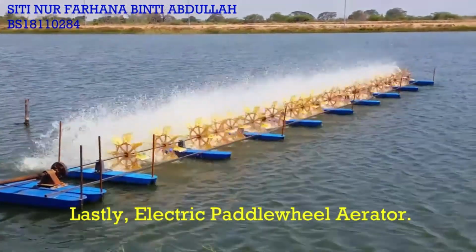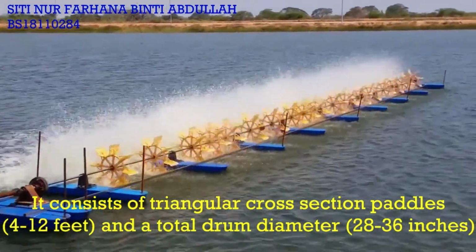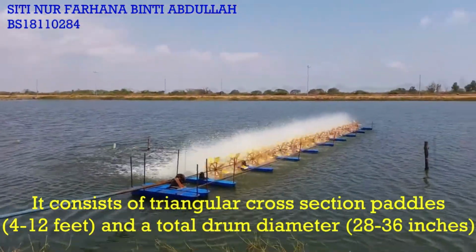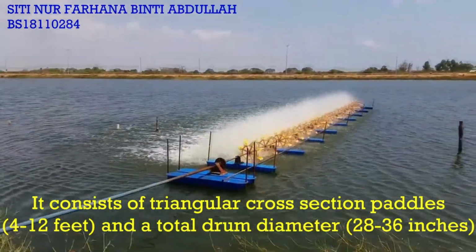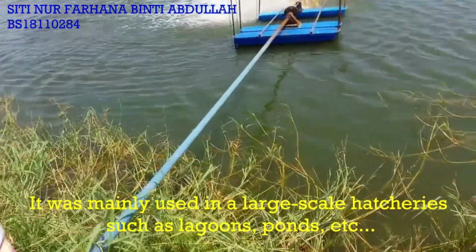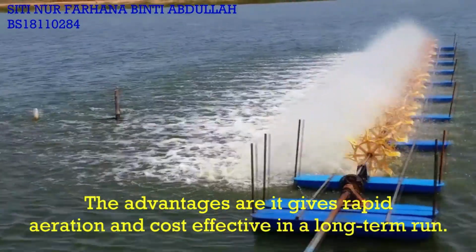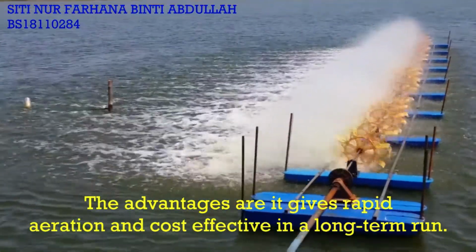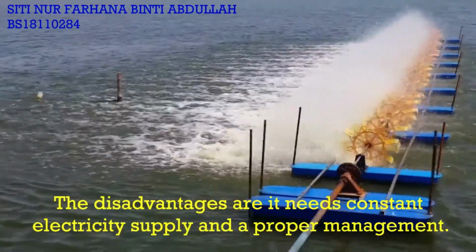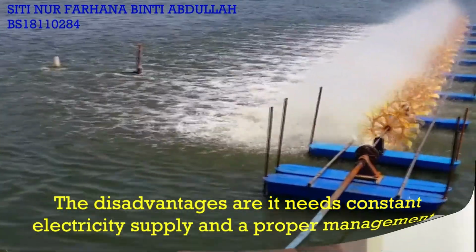Lastly, the electric paddle wheel aerator. It consists of triangular cross-section paddles from 4 to 12 feet long and a total drum diameter of 28 to 36 inches. It was mainly used in large-scale hatcheries such as lagoons or ponds. The advantages are it gives rapid aeration and is cost-effective in the long run. The disadvantages are it needs constant electricity supply and proper management.